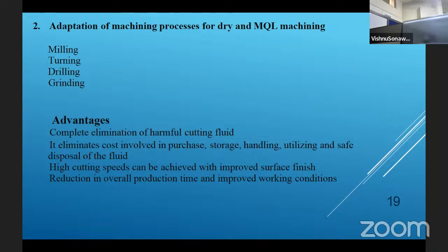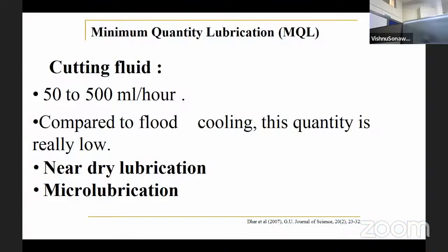And the cost involved in purchase, storage, handling, utilizing, and safe disposal of the fluid is saved, and high cutting speed can be achieved, surface finish will be improved, and the overall production time is reduced and the working condition will be improved. These are the main advantages of minimum quantity lubrication, right?